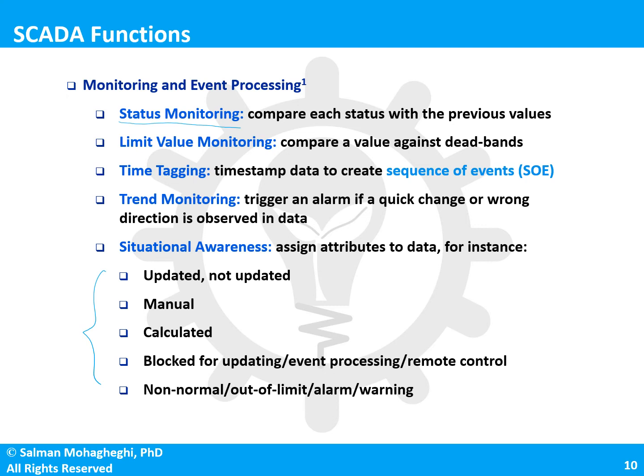So that indicates whether the value you have received has been directly measured or indirectly calculated. There are other attributes. For example, a particular data point may have been blocked for whatever reason the operator deems necessary, or it may be out of range based on an upper and lower threshold that you define, or perhaps going through values that are not normal based on the historical data.